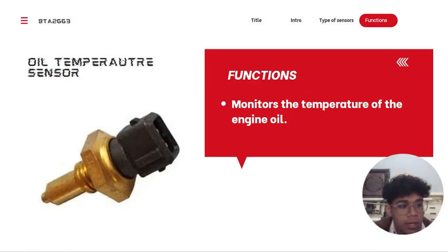Although many cars only have an oil pressure sensor and do not measure oil temperature, measuring oil temperature can be a useful additional layer of protection. If the oil overheats, this is going to negatively impact its viscosity and the oil won't be capable of doing its job, which can lead to engine failure. By noticing the issue by seeing the oil temperature, the ECU can activate the limp-off mode or refuse to start the engine before